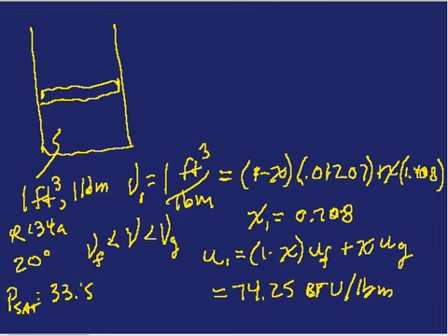We said it was a frictionless piston, so I'll indicate that that's well lubricated. And we're going to rise that weighted piston, such that as it rises it has the same weight, so the pressure is going to stay constant. So this is a constant pressure process, and the work is equal to the integral of P dV.